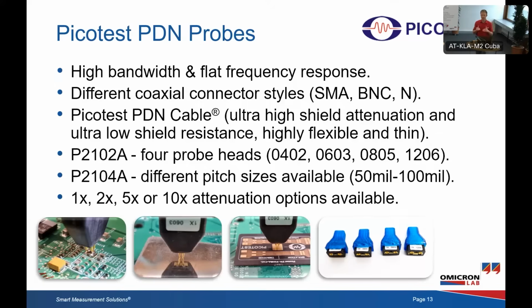So if you have very low voltage systems, the 1x probe is fine to go. If you have higher voltages like 3.3, 5, or 12, then you should use a probe with included attenuation.